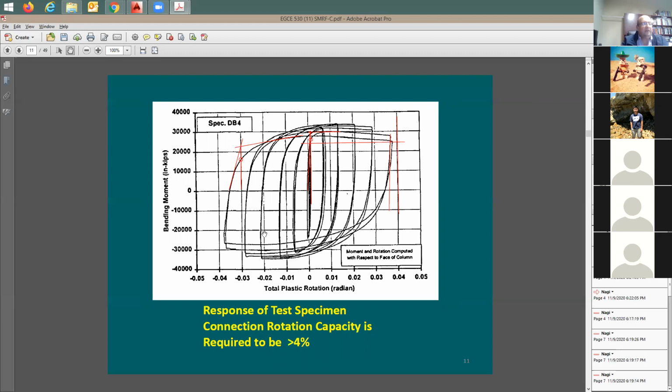And actually, if you're doing a thesis or some research, part of what we do after we do some testing is we look at the area contained by this loop. And we have a software, you can build a software for yourself. You say for each loop, how much was that area? And then you try to convert this area, because this area is going to be based on force and displacement. You remember the equation for the work done?